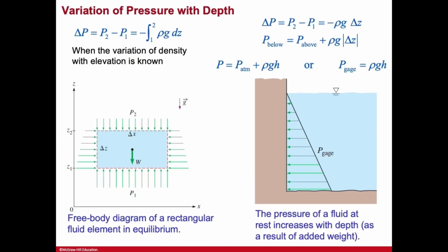So pressure, as we talked initially, is nothing but force over area, right? So if we are considering a volume of fluid as given here, what is the force because of this fluid? What is the force acting because of the fluid? It's just the weight, right? So your force is nothing but just the weight of that fluid because of this volume right here.